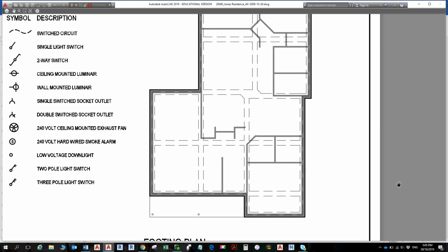So now we're looking at a slab level plan. At slab level we're seeing the walls and the slab edge, and anything below the slab is dashed, which is the footings and the post footing pads. The posts are obviously higher, so they're not dashed.